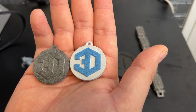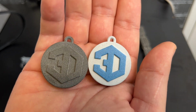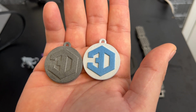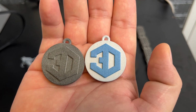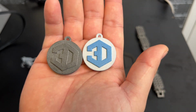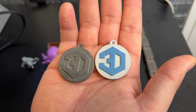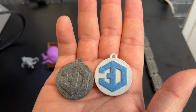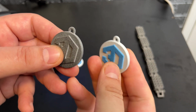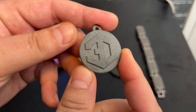It has high strength, superior in producing durable, detailed, and dimensionally accurate parts. The materials that are used are nylon, polypropylene, and TPU, which is a flexible material. You could find those using the multi-jet fusion, but JLC 3DP offers the nylon here, which was what we have as our samples. And it uses fine-grained materials to produce high-density parts that are optimal for functional use and mechanical application. And I wanted to get two examples of this, one in full color, which it offers, which I find to be amazing, and also without it being colored.